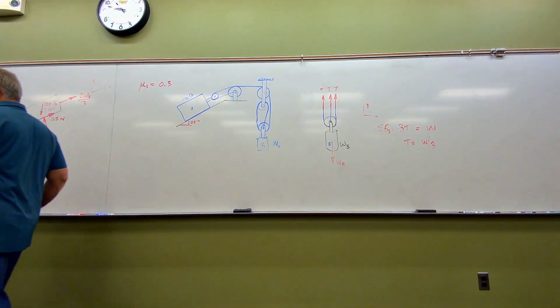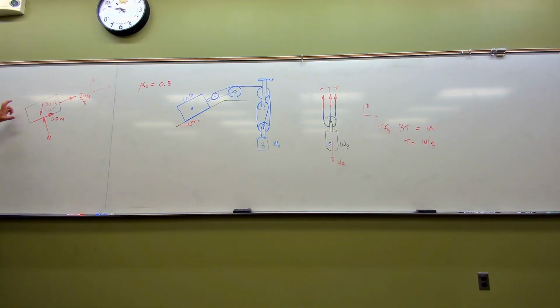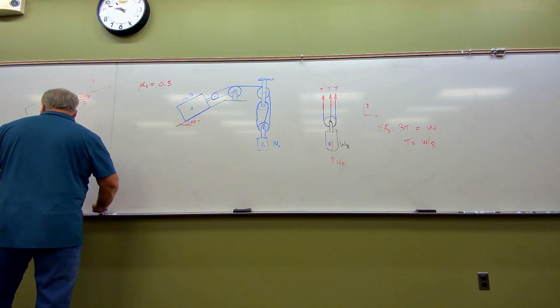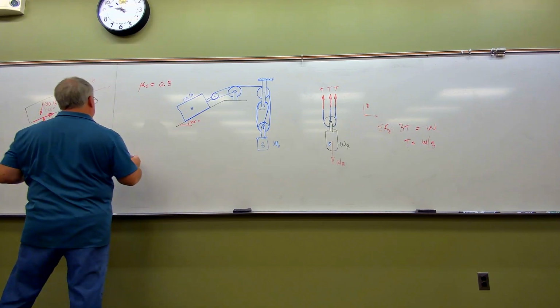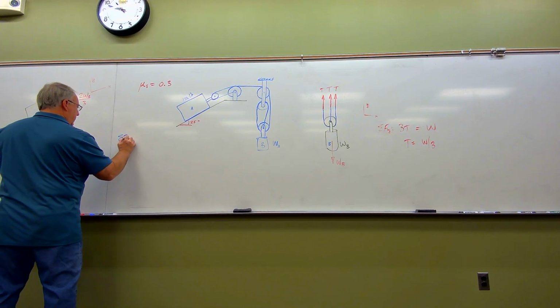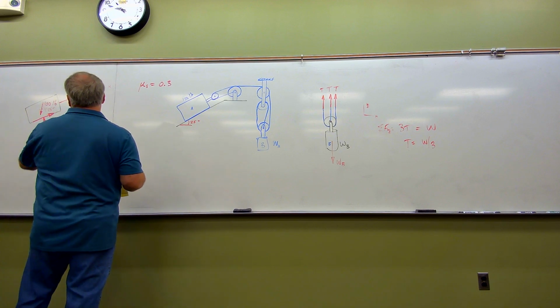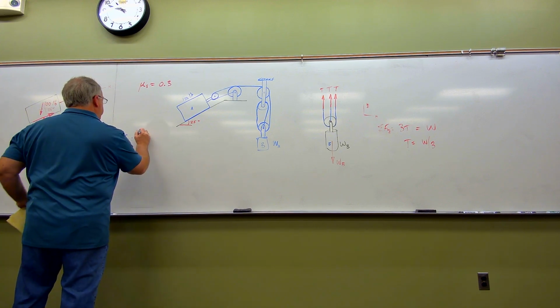If you think about the free body diagram that's in front of us right here, we got the sketch, we've got the axis system, we've included all the forces of what we used to be in contact with, the weight, the normal force, the friction force, they're all there. And now we've got nothing left to do in solving at least the first portion of this problem than just the equations of equilibrium. So in following the same old, and remembering the 2, we define our x-axis like this. If I now sum my forces in the x direction, I will have the following. I'm going to have 2 times WB over 3.